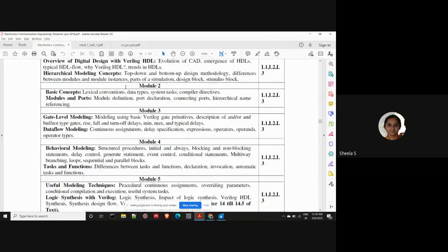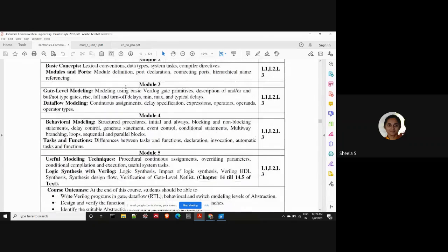The main difference between Verilog and VHDL is that, compared to VHDL, Verilog is a bit more user friendly. For example, if we miss mentioning some part of the information, it will presume it. If I consider two 8-bit numbers, and instead of an 8-bit number I give only a 4-bit number, that is one nibble, it will do the extension to 8-bit and won't show any error; it will read the data.